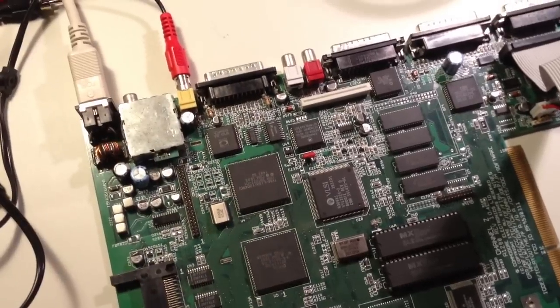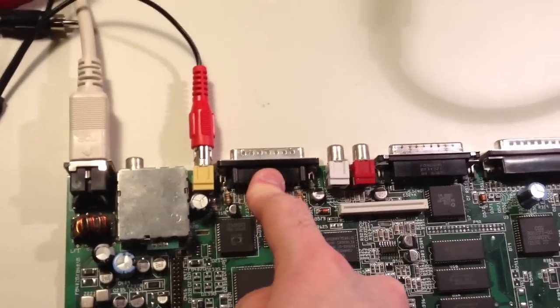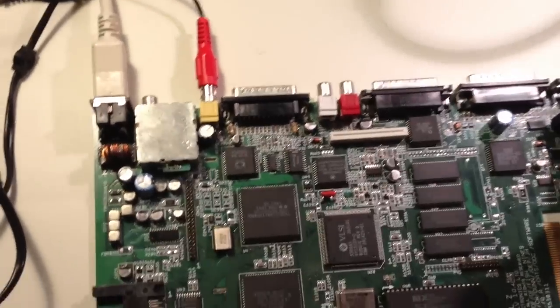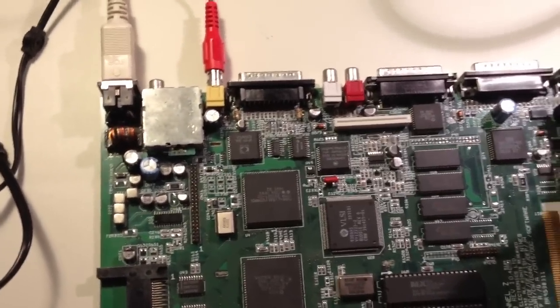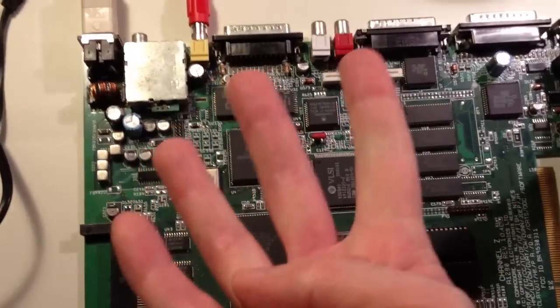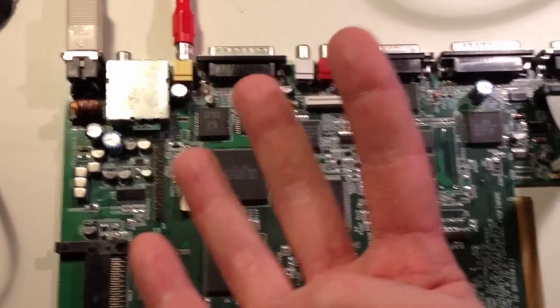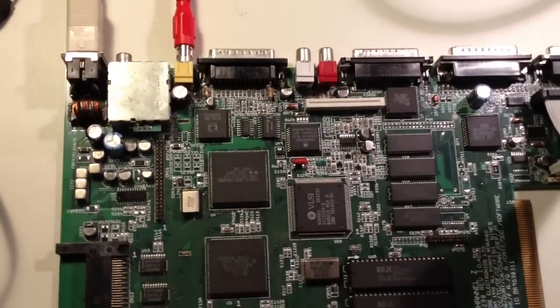Okay, so why am I getting a picture from the composite video output but not from the RGB output? Let's see here. There are 5 signals needed in order to produce an RGB picture on the TV. First we have the RGB signals, red, green and blue, and then there's the composite sync signal, which contains a lot of sync pulses. There's no video information in there. And then we have the switching voltage in order to switch the TV into RGB mode.